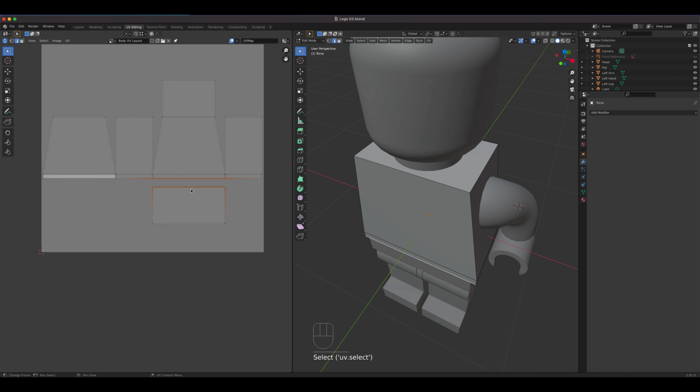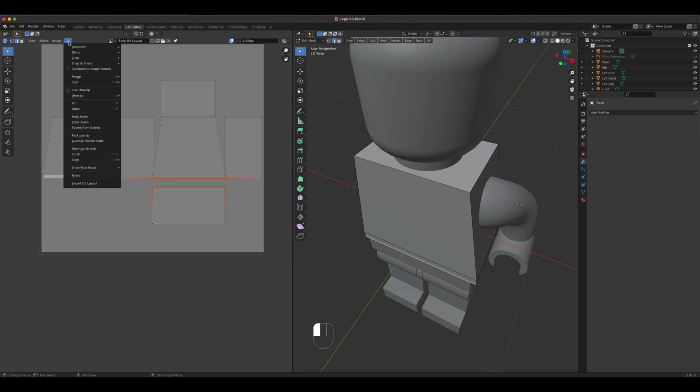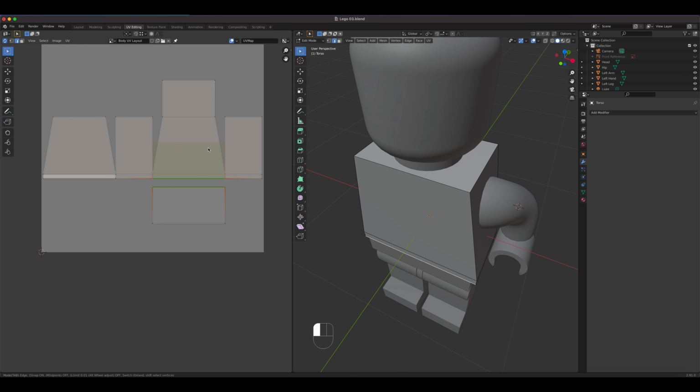All right, let's preview this one. Let's see if it connects to this one. UV stitch. It's still going up this way. For some reason it wants to flip it. All right, so let's flip this one here. I'm going to escape to cancel that one. I can rotate this, or I can also do S Y -1. It flipped it over this way, vertical instead of horizontal. Let's take a look. Okay, it's saying that's where it belongs right there. So we can do UV stitch and it jumps right there. Press enter. All right, and there it is.